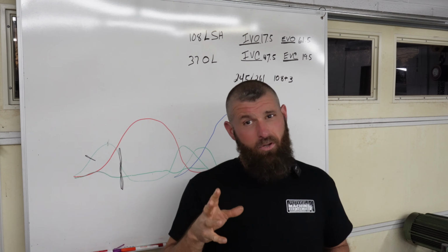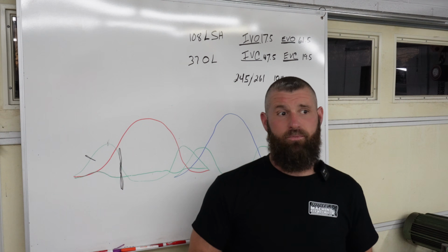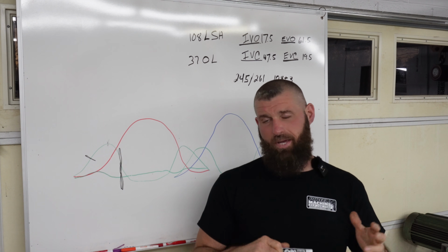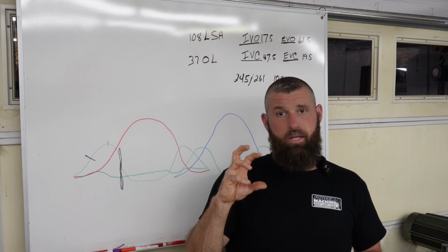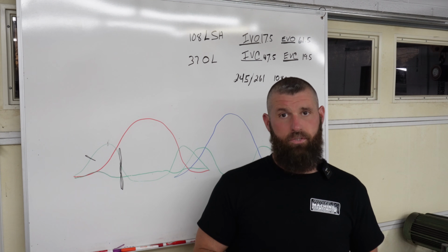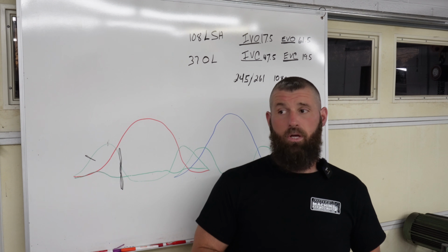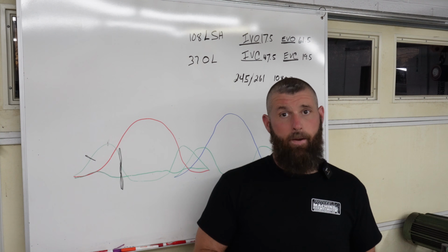So it's probably going to be hard to get there and keep the CCs down, and so it ain't just, we got coefficient of discharge. That's a whole nother topic. But in a good conventional cylinder head, you can get to mid to upper 320s without too much trouble and keep the CC small.